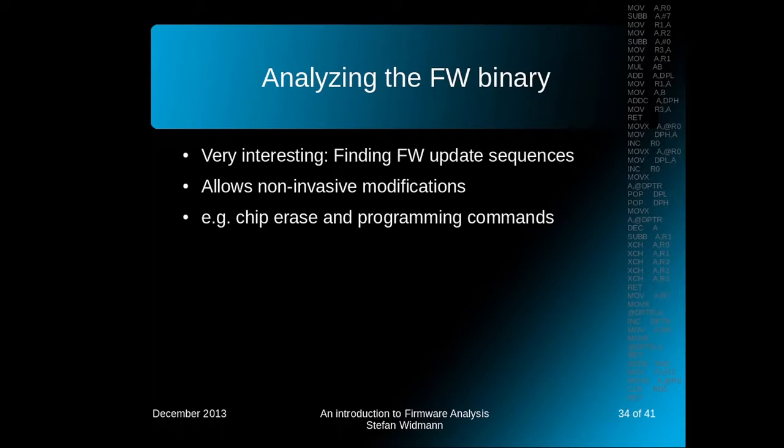It's very interesting to find hidden firmware update sequences, of course, because they would allow non-invasive modifications. For example, search for chip erase and programming commands. You can take the appropriate commands from the datasheet if there is any external memory device available.